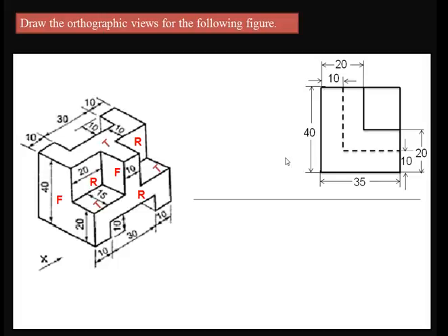Now from this front view we can project the top view by drawing the construction lines from each and every side or edge of the front view. Draw the projection lines or construction lines like this. After this I want to analyze the shape again. In the top view, whatever the T letter I have represented, those surfaces we can see. When you join all the surfaces we can see a particular shape. Initially, in the top view, assume this edge as a straight line.